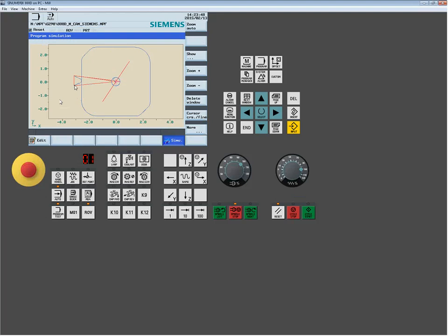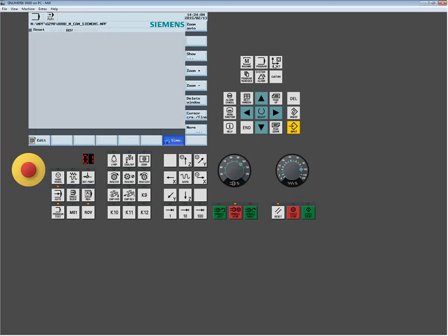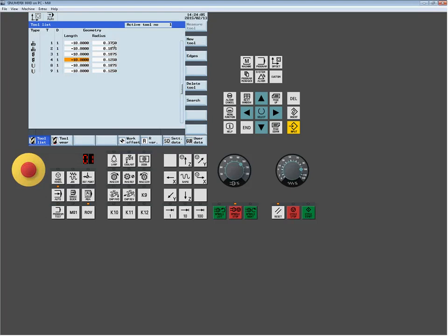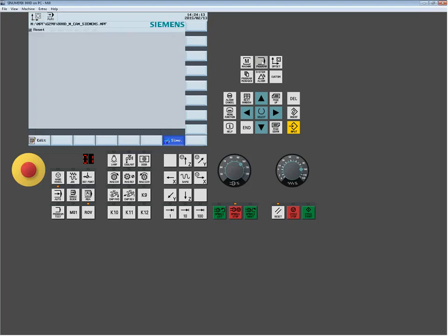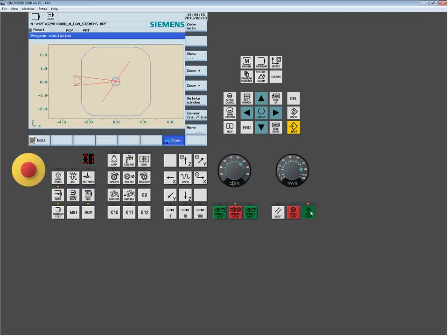What's happening right now, and what you don't know, which I already know because obviously I set all this stuff up, is that we think that this machine should be running tool 1. Well, the way the parameters are set up in this machine, it's loading the offset based on the T code, not necessarily the M6. So one of the first things you might do would be say, well, what would happen if I went to tool 1 and I dramatically changed my radius to maybe a 0? What I would expect to happen when I simulate it is I would get a different result.